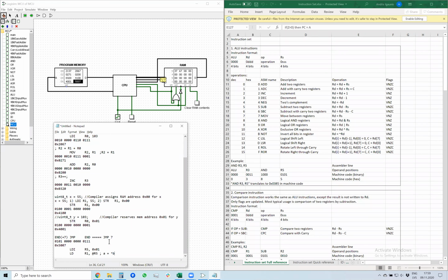Okay. And most processors have this really cool thing that you can also tell it to auto increment the pointer after this instruction. So register R5 contents go to the address line, register R1 is reading from the data line, and register R5 is also thrown into the arithmetic logic unit increment instruction, and its value will be incremented by 1.